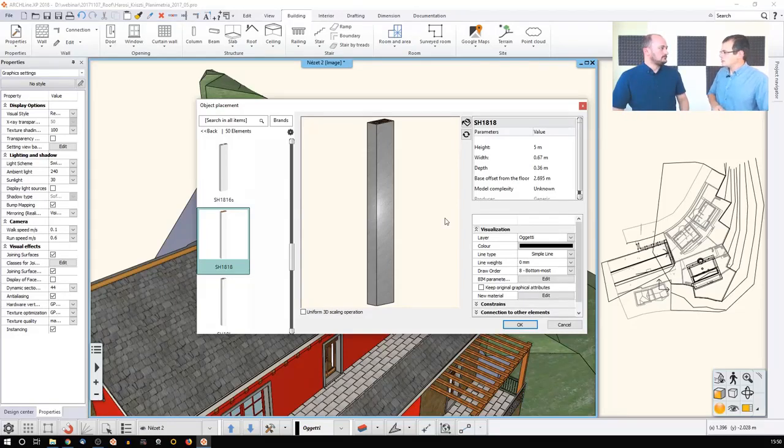I know that there's one thing regarding objects that we have to know about, and that is namely with sections and elevation drawings. By default, as we covered two sessions before when we talked about how you can create sections, the section hides the objects, because the architectural section is usually for structural reasons, and that's why it's hiding the cars and the chairs and the tables and everything else. If you place your chimney as an object, it will be treated the same way as the rest of the objects. So in that case, you just need to make sure that either you turn this option back on, or you create the chimney in another way when it's not interfering with that setting.